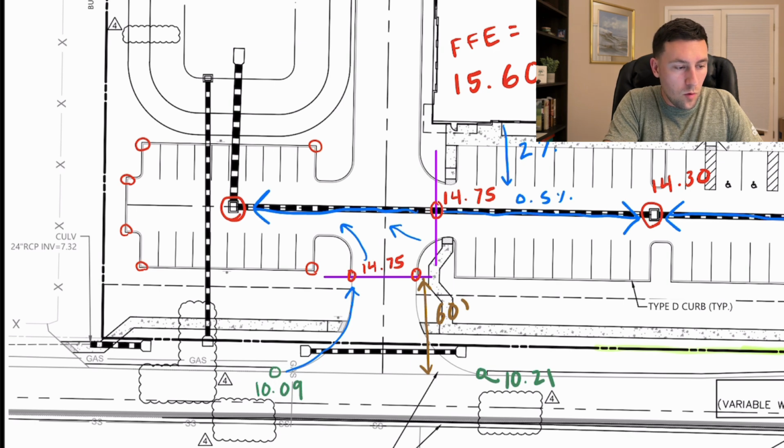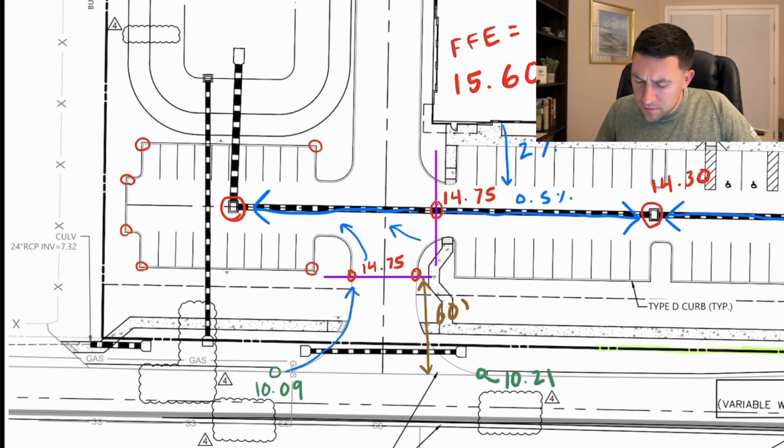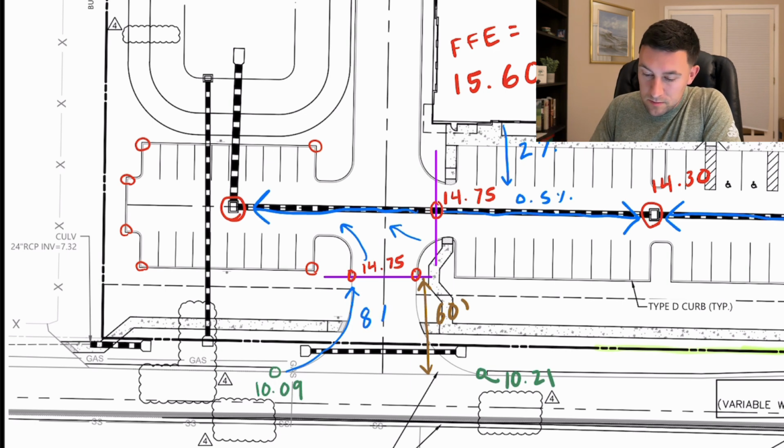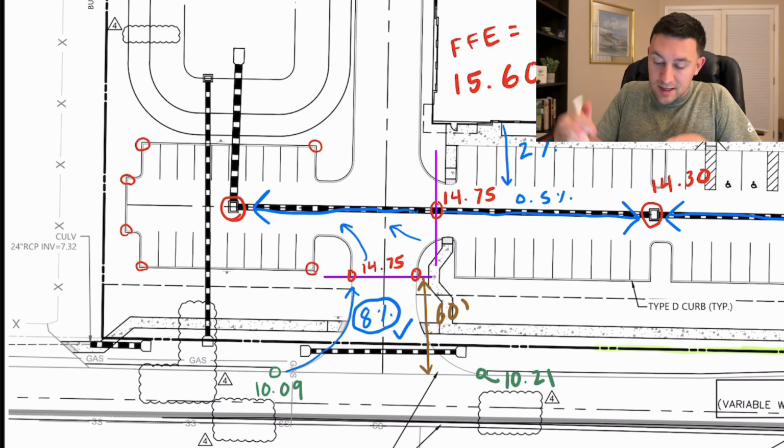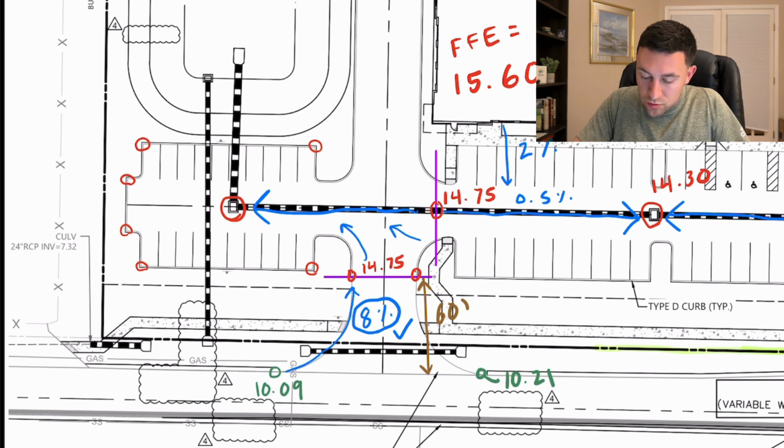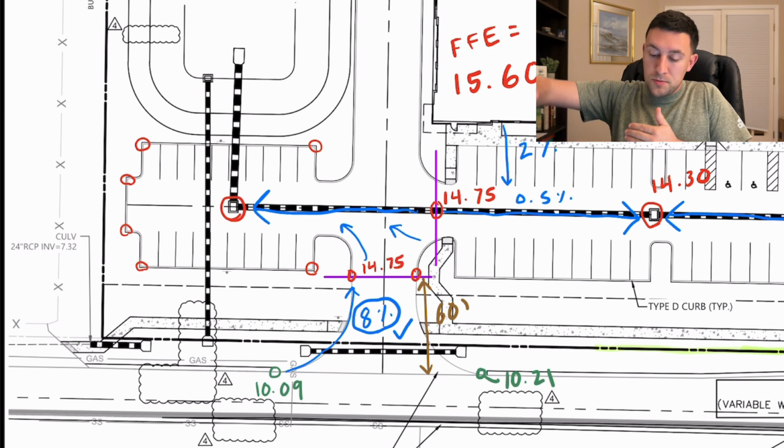So that's a 4.66 drop. Okay. 4.66 drop across how many feet did I say? I think I said 60. All right. 4.66 drop across 60 feet is 0.077. So what I will say for that guy is a check mark. We have around, let's call it 8%. We have an 8% increase again from this driveway point that we're building new driveway up to a high point.